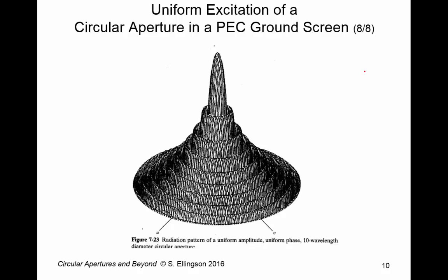Okay, here's a volumetric antenna pattern in terms of the direction cosines, u and v. I've talked about those in a previous lecture. So this is what the pattern looks like. This is obviously the main lobe, first side lobe, and so on. So sometimes these pictures are useful in visualizing the pattern. It's not surprising to see that the pattern's radially symmetric, so the side lobes form rings around the main lobe.